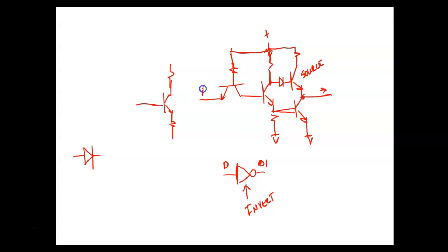Now, if we came over here and put a 0 in here, I'm sorry, that was wrong. If we put a 1 in here, it would transfer here and turn this one on right here. And what this would do, it would take the output and just connect it to common. And that was a 0. But current was flowing into the gate, so the actual voltage had to come from somewhere else, right? You understand that? And this became known as the sinking transistor.